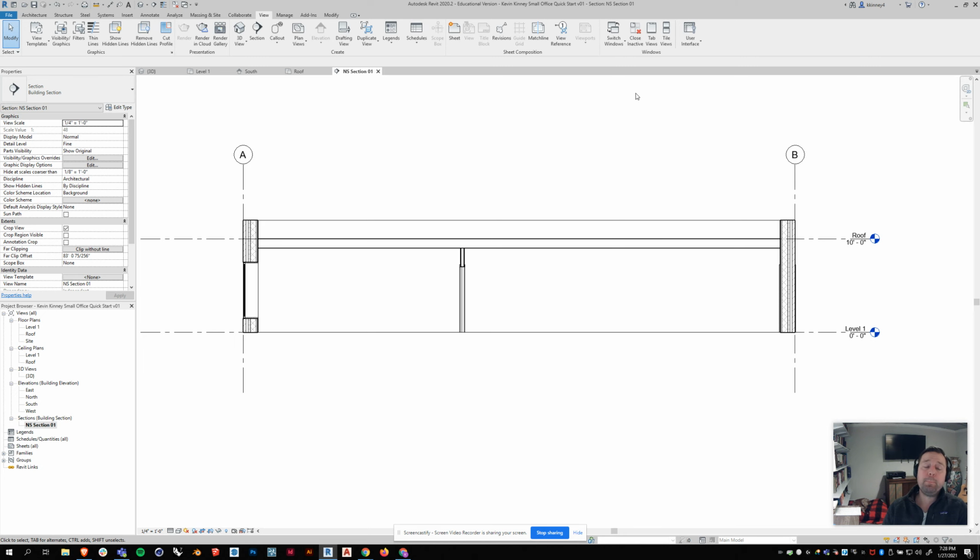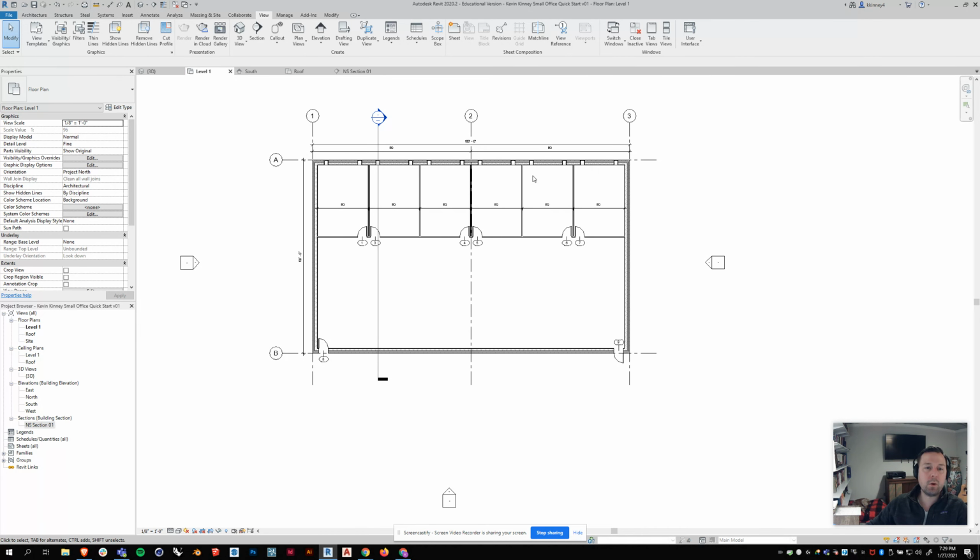Okay, let's make a floor real quick and we'll be done with this lecture. I know I'm rambling. Okay, so we want a floor at level 1. I want that floor to happen right at level 1, and all of its construction should happen below level 1 so that when my feet are on level 1, they're actually on level 1. So let me go to level 1, floor plan.